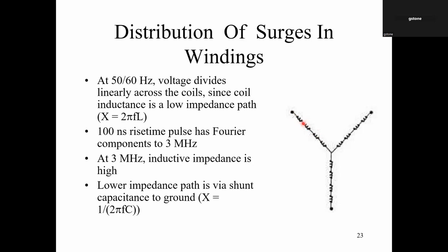And there I've talked about the coil, but the same thing happens on each individual turn. There's also capacitance between the turn and ground, although it can get very complicated because the turns might in fact be far from ground. So it's a very complicated, messy circuit. But I think you can understand the basic principle is that capacitance, even on the first turn, might be so high that the current goes through that first turn and immediately is effectively at ground potential. That means instead of having just 1 or 2 volts across the turn insulation, the polymer film on the magnet wire, you're going to have possibly the full voltage.